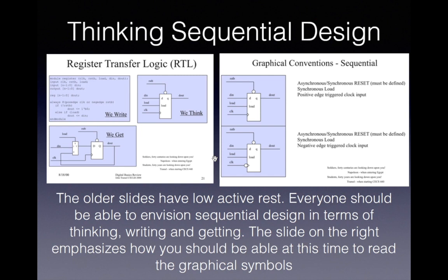When we go to capture a digital circuit, the first thing I want you to be able to do is to itemize the ports. And that is the purpose of the top level block diagram under the we think. I know that within that block there's a certain amount of logic. But initially, before I design that logic, I want to say, okay, I just need this.